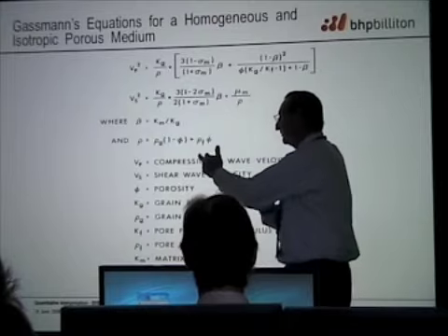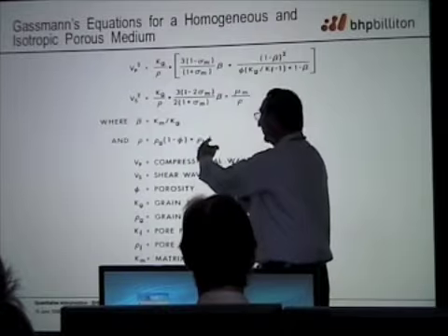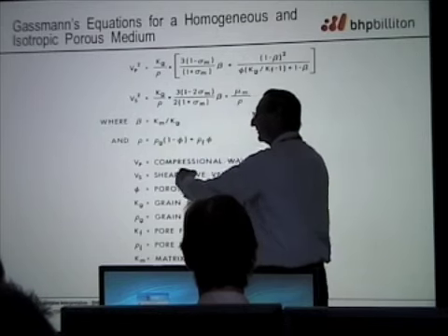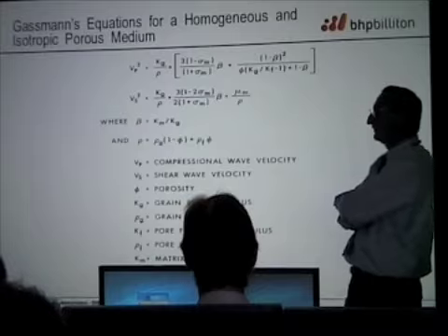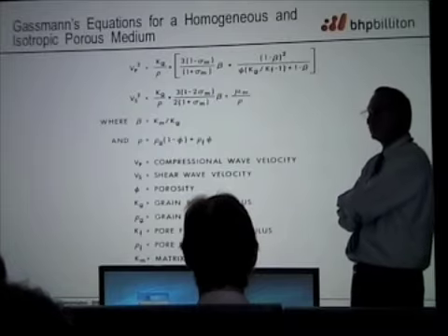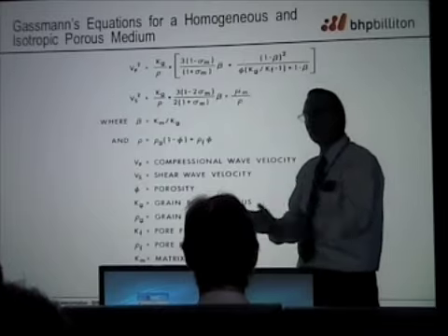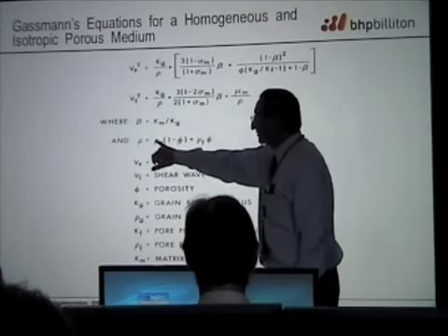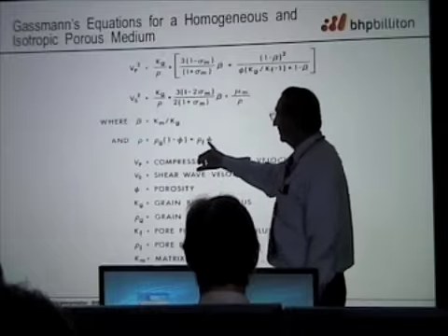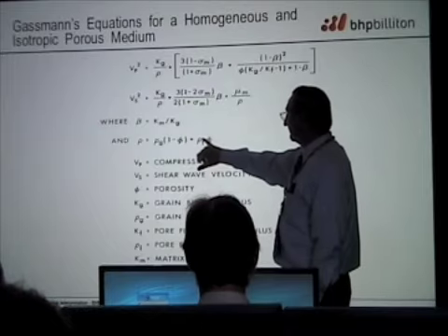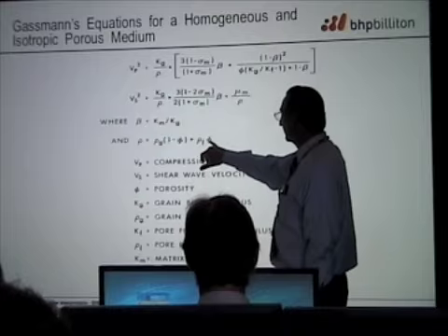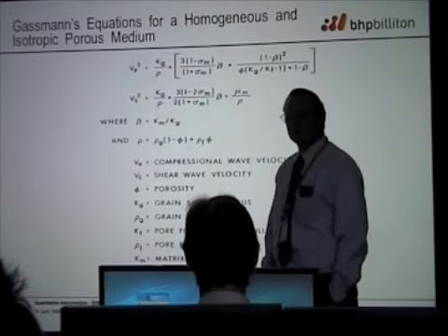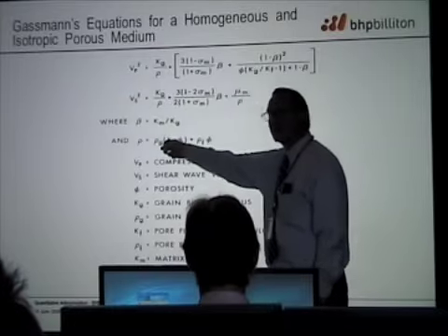Let's make it 2/3 here and 1/3 there, it's easier. 2.65 times 2/3 is 5.3 over 3. Roughly 1.8, right? So 1.8 grams per cubic centimeter from this term, which doesn't change. And over here, when I have the brine in there, I've got 1 times 1/3, so that's 0.33. That's about a sixth of what this is.